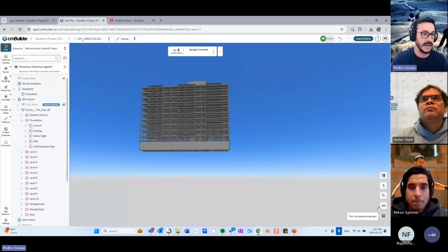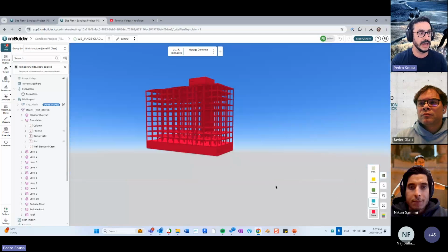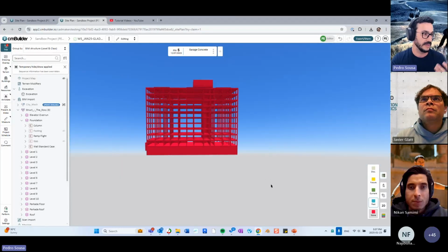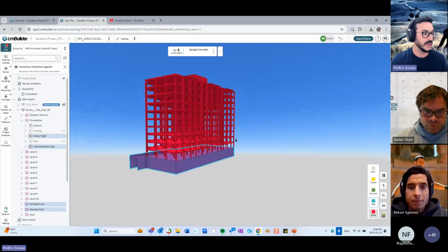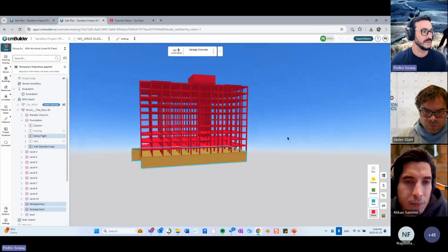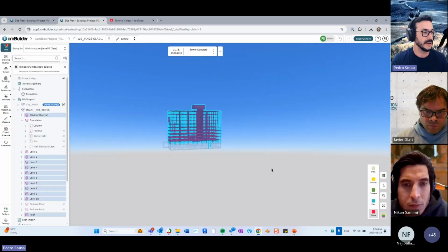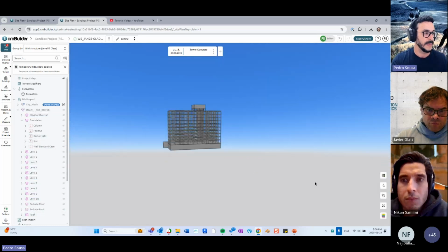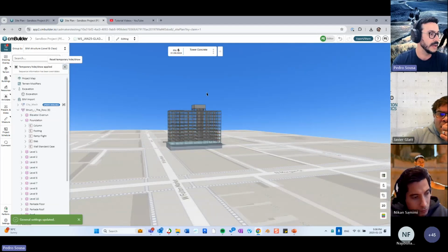And then I like to work with this view over here where I can see only the elements that haven't yet been connected to the milestones. And from this, I will put the garage concrete on this milestone using Control B, and the tower concrete on this milestone using Control B as well. So now, very quickly, I have a,